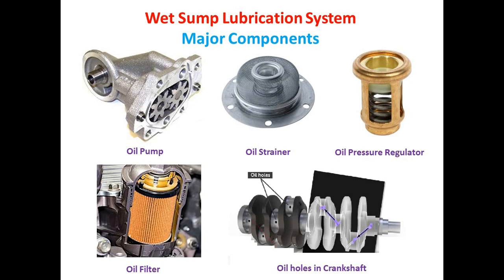Next, we have the oil filter. Most of the oil from the pump goes directly to the engine bearings, and a portion of the oil passes through the cartridge filter, which is exactly shown in this slide. So this type of cartridge filter removes solid particles from the oil.